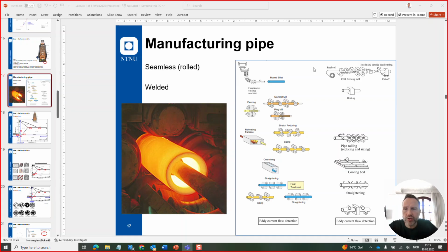Then this drum is hoisted on board a boat or wherever you are laying your pipe. If it is in the desert, it will be on a huge truck. And then what you do is you stop whenever the drum is getting empty and you weld it together with the pipe on the next drum and you continue laying your pipe. Line pipe.